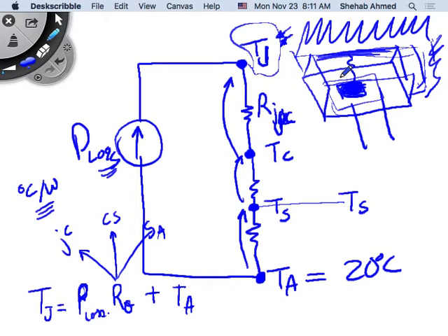Or this case can be designed with a thermal pad in the back to improve thermal conductivity and dissipation of the heat to the ambient environment. Or this case can be put on a heatsink, with thermal grease in the middle, or with another thermally conductive, electrically isolating material, right?